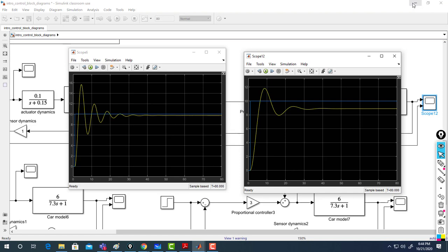Later on, in the next chapter when you study the effect of the integral term, you will see that the integral term can make a stable system unstable. So it's risky to increase the integral term, even if your system was stable without control.